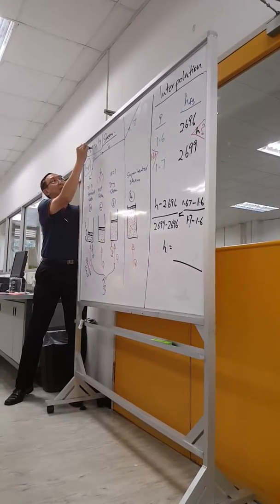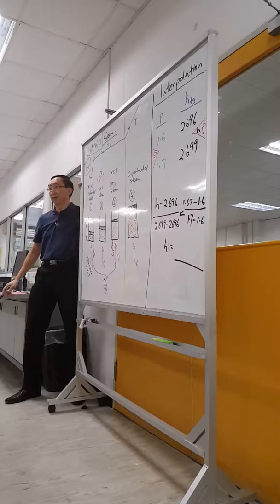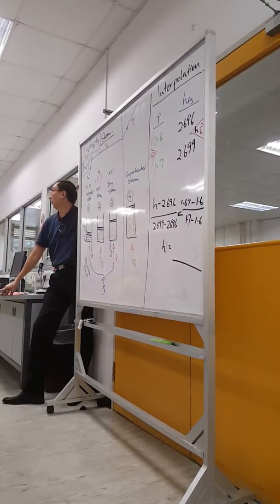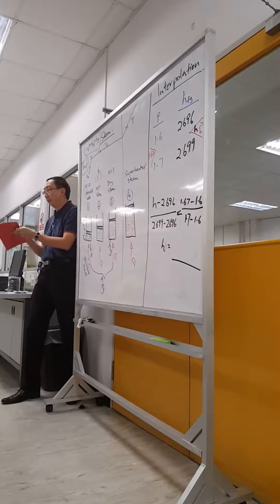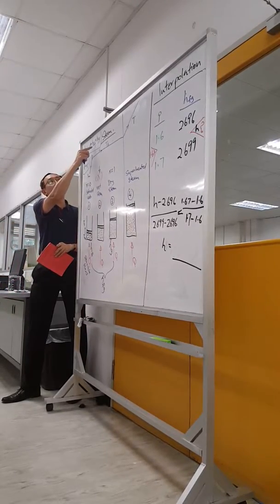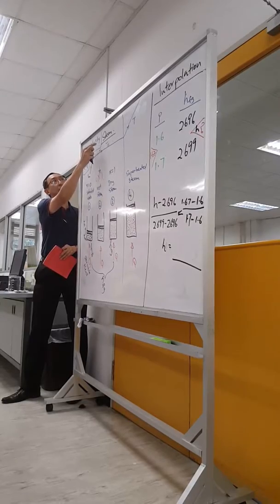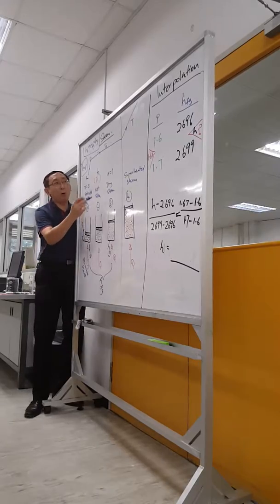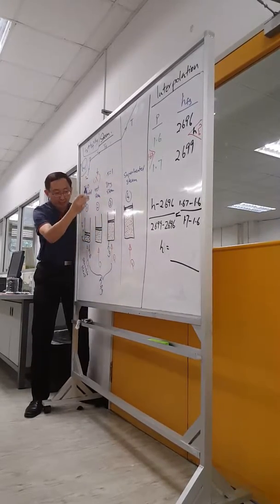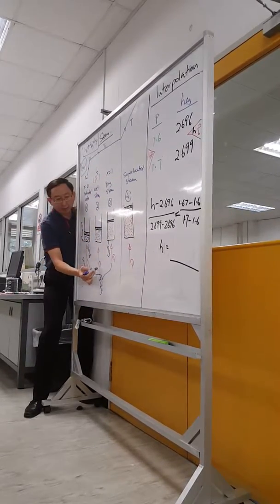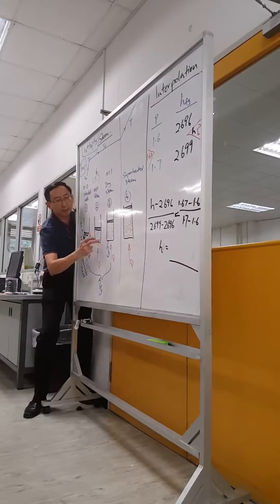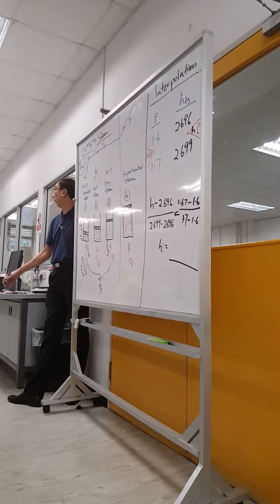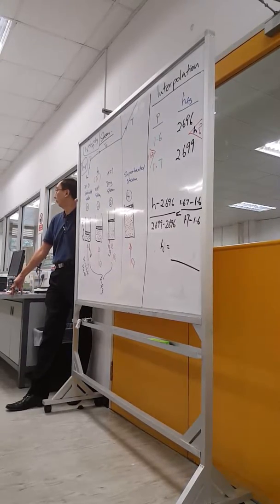So this plus this must be equal to this, right? That's what is given in the note. If you look at your steam table, there are 3 columns, HF, HFG, and HG. If you add these 2, you'll get this one. So in order to get all totally dry, I need HF plus a certain energy HFG to transform them to steam, totally dry. Any question?